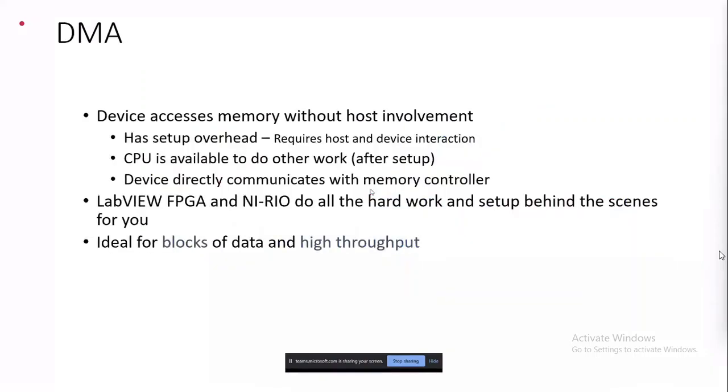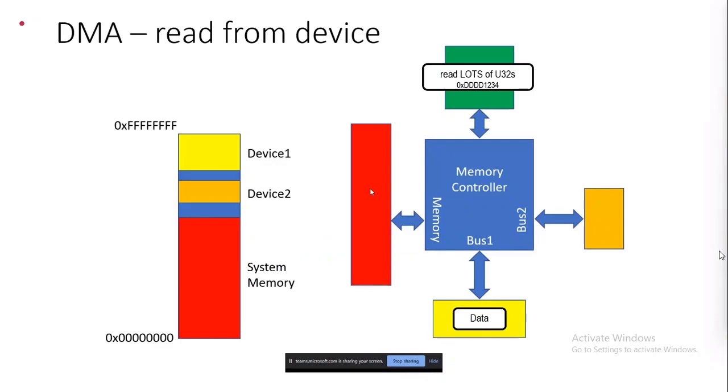We go for something called a DMA FIFO. This is a memory or rather a data transfer mechanism which runs without CPU involvement. So what happens is, in the beginning, the CPU programs the memory controller, saying take a lot of data from the memory, from where to where you're supposed to take it, and then send it to your USRP. Or rather read, in this case read, fine.